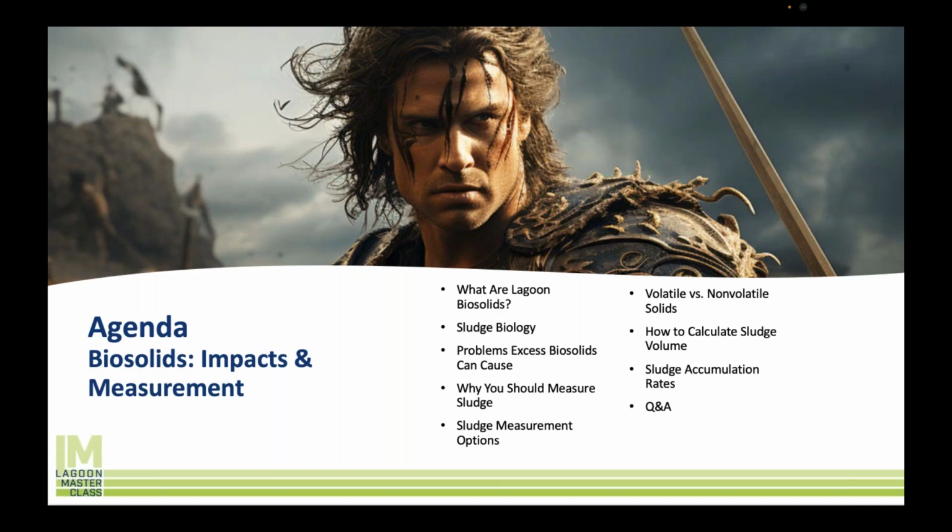I often hear people say things like, lagoons don't work, or our lagoon stopped working. And most often, the reason that happens is because they have too many biosolids, and they have not managed their biosolids, or they can't remember the last time that they removed biosolids. They have no idea how many they've got. To complain about lagoons that way, for me, is like driving your car, never changing your brake pads, and then saying, well, the car doesn't work because I got in an accident because I couldn't stop. It's like, no, the car works just fine. You just gotta change your brake pads every once in a while.